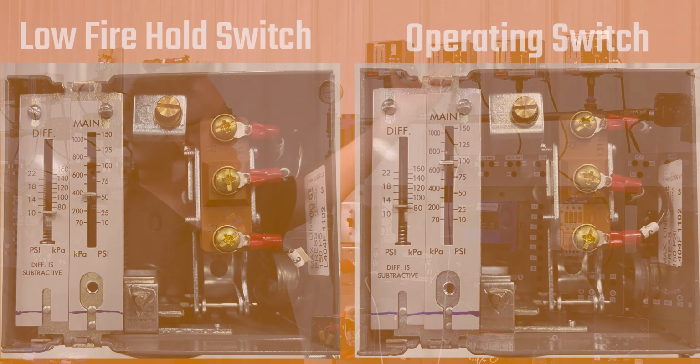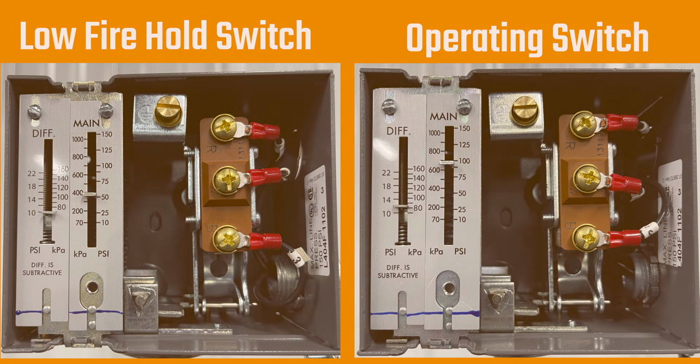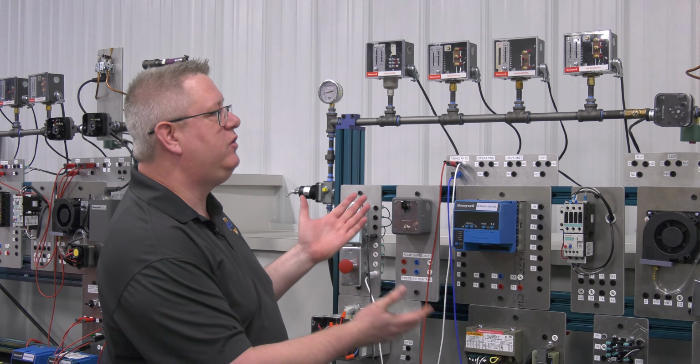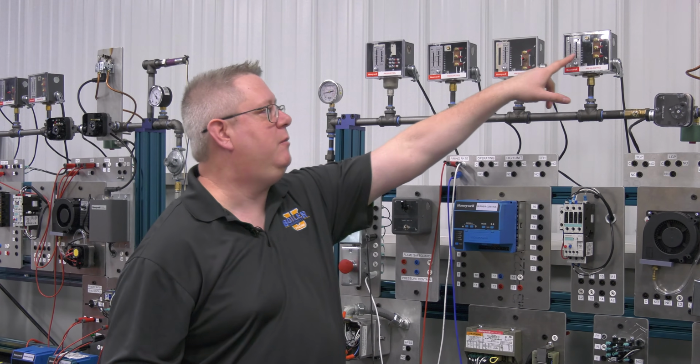Now our operating switch and our low fire hold switch can be a little trickier because in many cases it's the same model, style, shape, number, and everything. So what we need to look at if we just walk up to a boiler that's in operation is the setting on them.